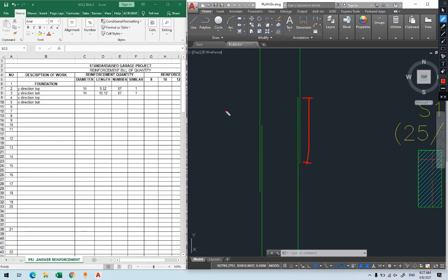You cannot just bring the steels to connect them like this. There are connectors. There are types that use connectors. They weld them together. But if you don't have these connectors, there's a way to just overlap them. They call it overlapping. Splice, how much is needed? 1 meter you can provide. But I'm not recommending just like this. There's a code, there is a calculation. But practically people provide it in this way.